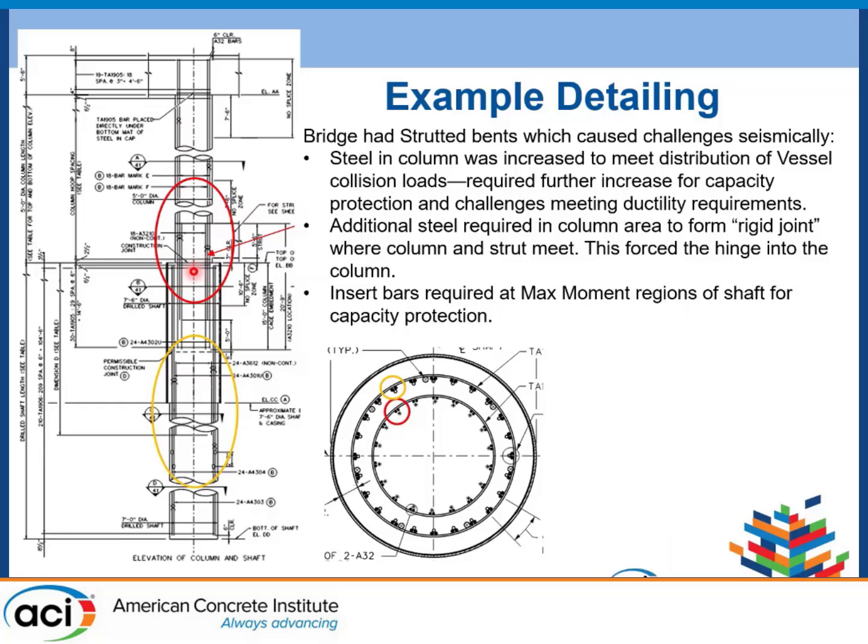We increase it by 20% and we design the elements, that are designed to stay elastic, against the demand imposed on that element by the column hinging. And we design so that we have enough steel in those elements, in some cases enough size, but certainly enough steel to facilitate those elements staying elastic.